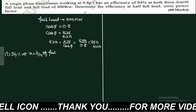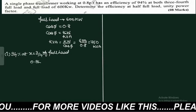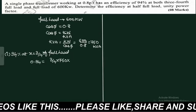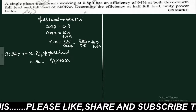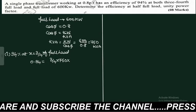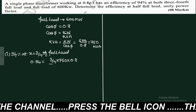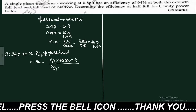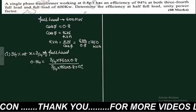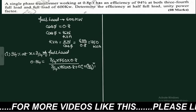Substitute into the efficiency formula: 0.94 equals 3/4 into 750 kVA, the full load kVA, into the power factor 0.8, divided by 3/4 into 750 into 0.8 plus Wi, the iron losses, plus the copper losses, which become x square, that means 3/4 whole square, into WCU.